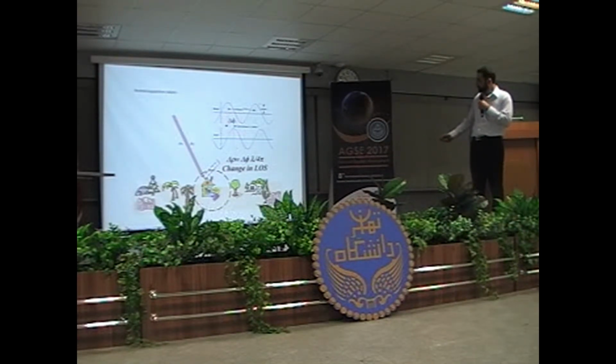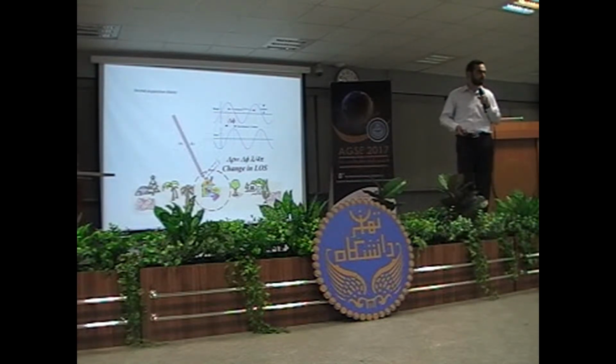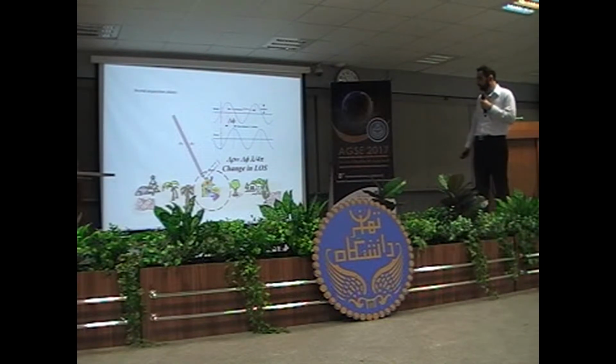See? So there is a very small difference between these two, the first acquisition and the second acquisition, a phase difference of delta phi, and this will give you an estimation of how much subsidence there is in that area. So this is the basic idea for the interferometric application.